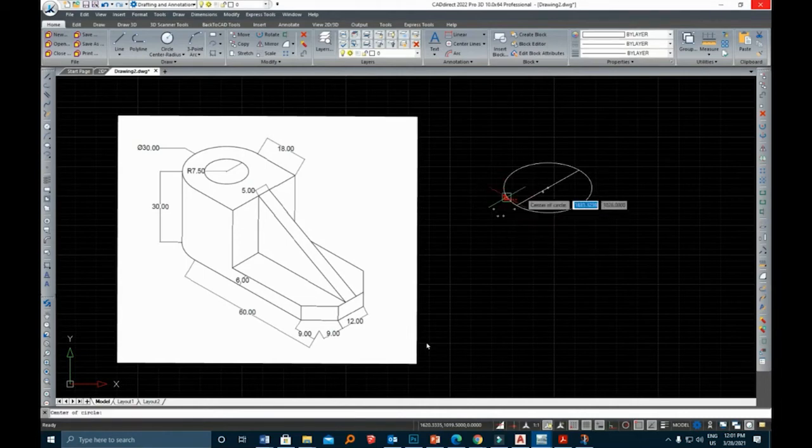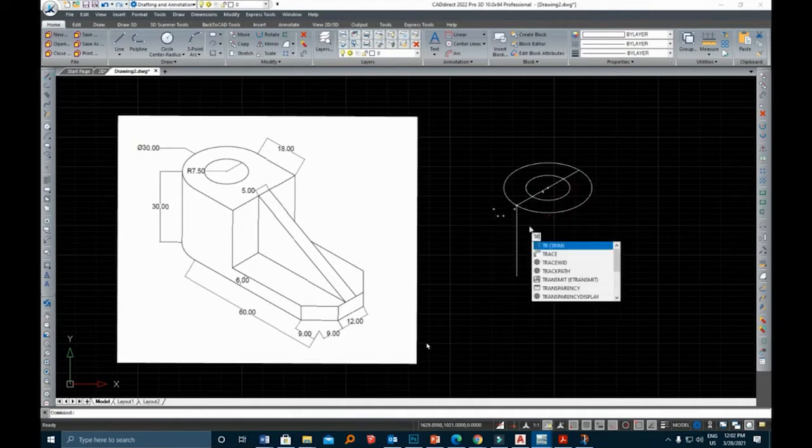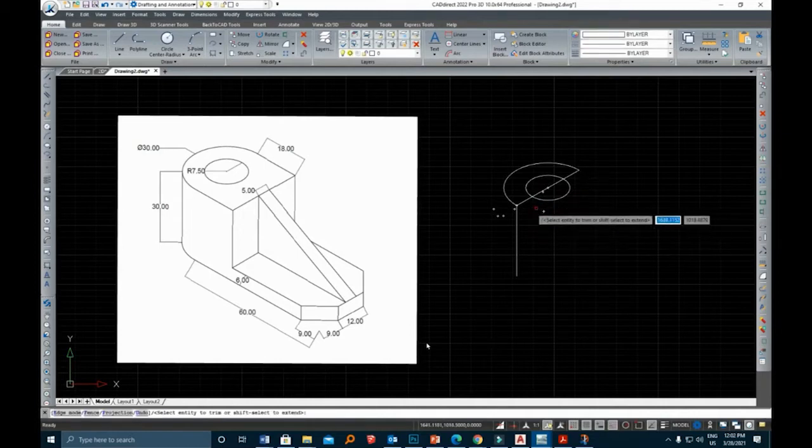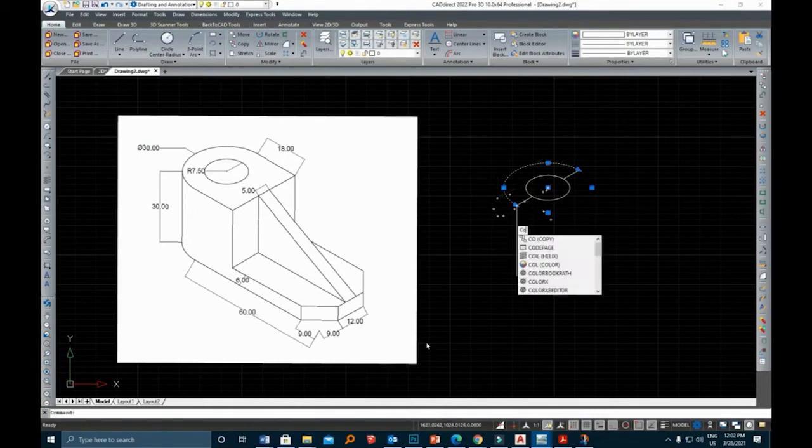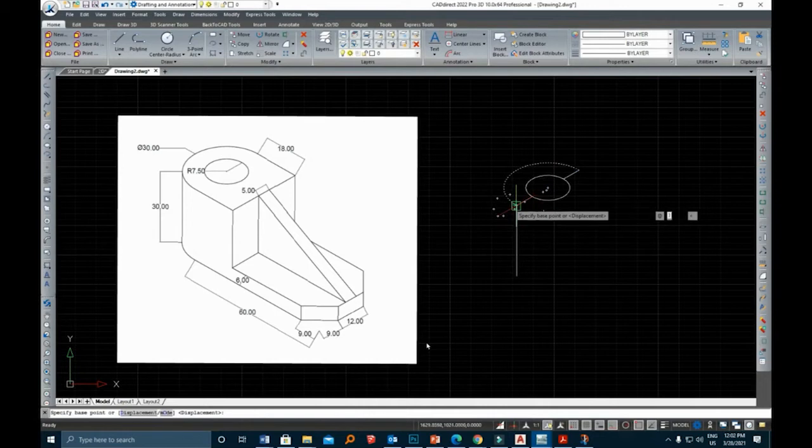So you can write down the radius there. I'm going to mention the height. It is 30 centimeter. I have given it with the line tool and trimmed the unwanted parts using the trim command. I'm just copying the above circle to the bottom. Now I'm joining the tangents of each of those circles.